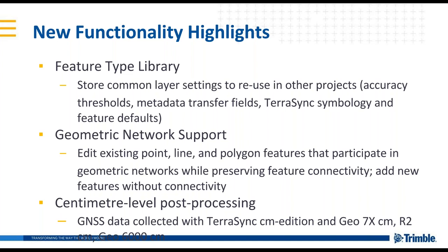So you could check those out, take them out, edit them, edit the geometries, and when you come back, those features will still be connected, and it'll adjust connected features. So if you take a hydrant and move it, and it's connected to a hydrant lateral, it'll move the hydrant lateral as well when it gets checked back in. So that's Esri functionality that now we are working with properly. If you want to collect new features, those features will be brought in, but they won't be connected to the